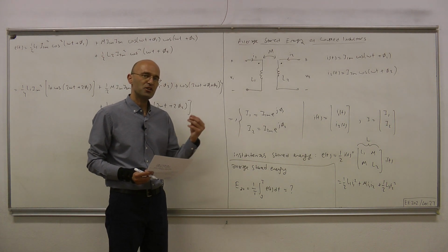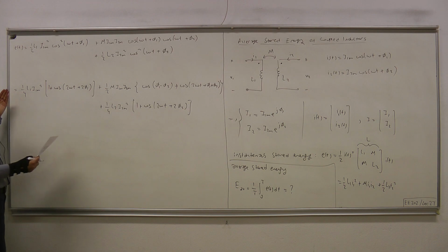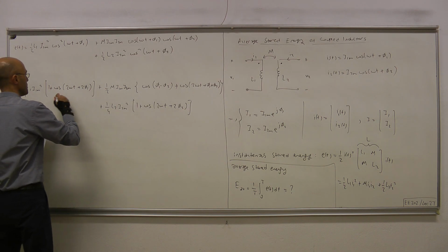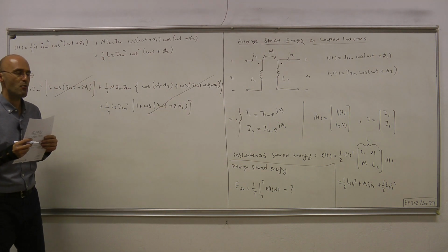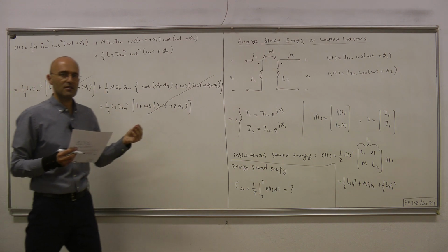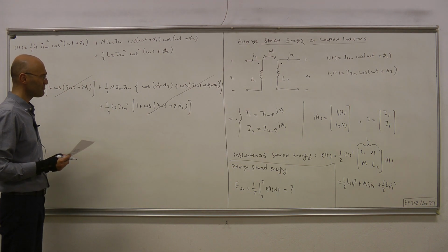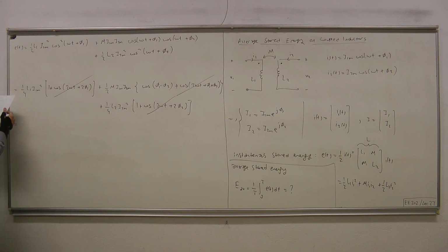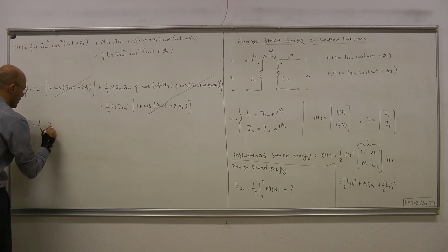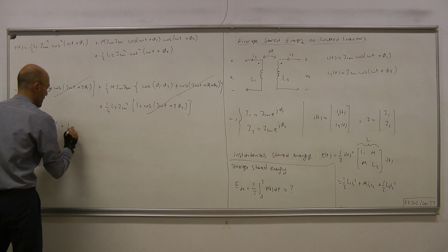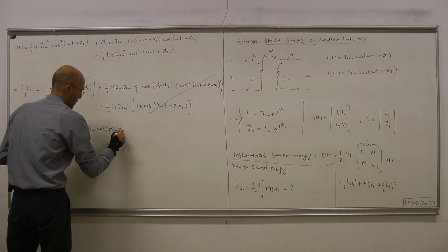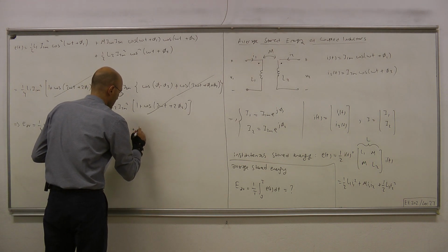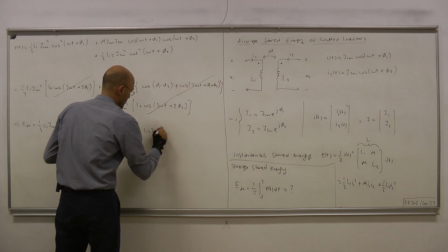We know that pure sinusoidal signals produce zero average. So when you compute the average of this E of t, this term will disappear because it's a pure sinusoidal function, and likewise this term disappears. And when those terms disappear, all the remaining terms are constant. Therefore, they directly come out intact out of the integration. What we have therefore is the following: E average equals 1/4 L1 I1m square plus 1/2 m I1m I2 magnitude cosine of the difference of phases plus 1/4 L2 I2m square.